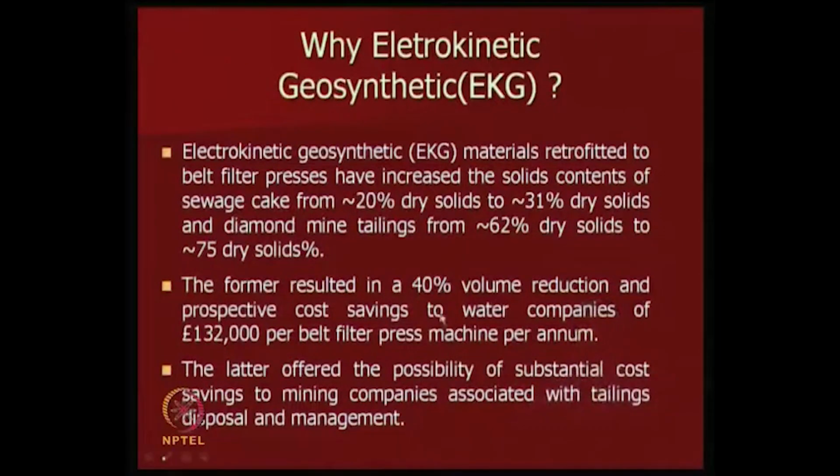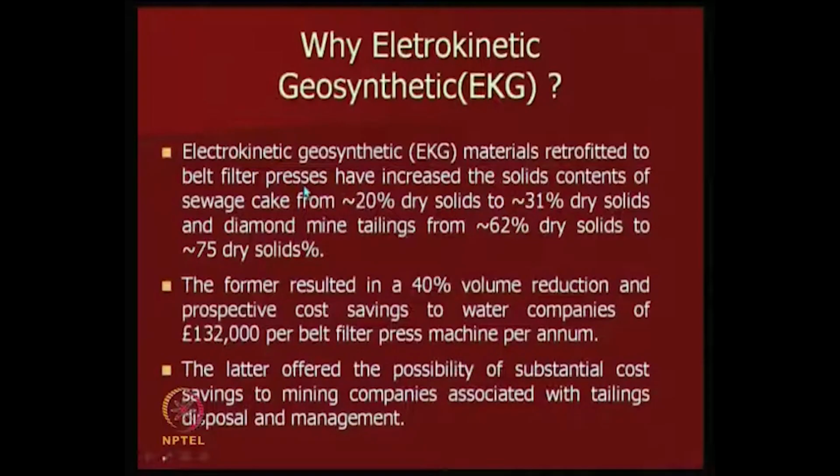So, to handle that, even in fly ash, for example, you have dry disposal and wet disposal methods. Dry disposal is not permitted because fly ash in the air could contaminate, but in the wet state it has too much water, so handling becomes very difficult. So what we try to do, in some other materials if not fly ash, is increase the solid contents.